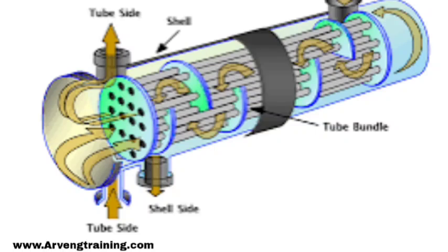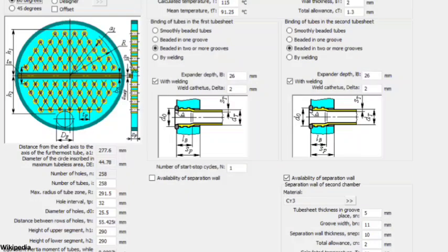Yeah, it's better. My question is about the tube sheet thickness calculation. Do you have to perform ASME UHX and TEMA both in the PV Elite calculation, or will any one of the two suffice the requirement? Anybody want to answer? I say UHX is the best option, and I don't prefer TEMA because it is not based on scientific research.